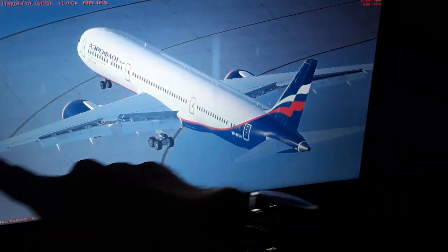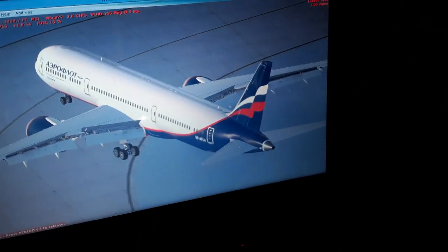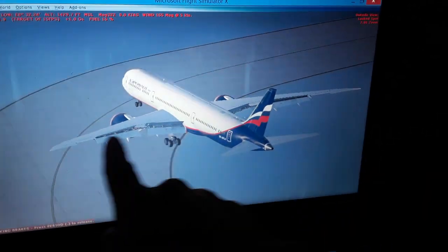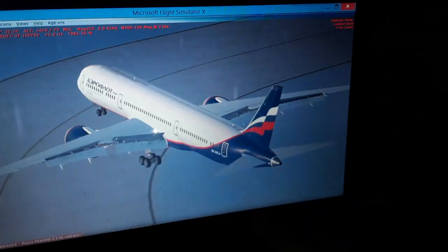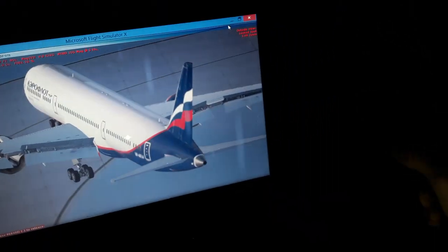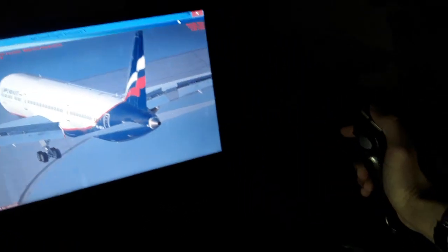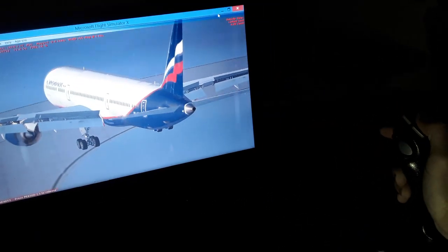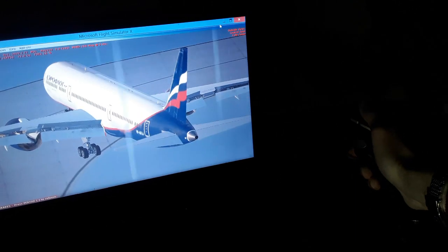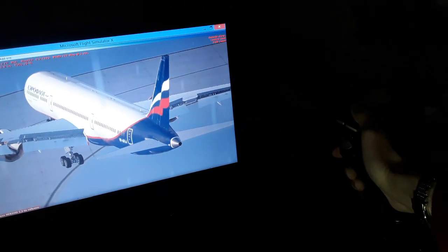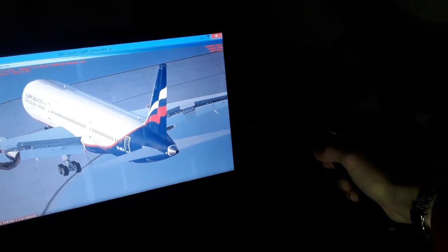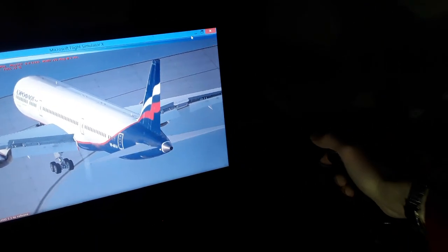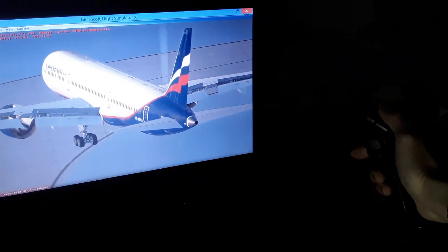We have also one more axis, the lateral axis, from wingtip over here to wingtip. It is the pitch axis of the aircraft. You use the pitch axis from the tail of the aircraft, the elevator over here, climb, descent. So you can climb the aircraft using the horizontal tail, the horizontal stabilizer in some aircraft, and also the elevator trim. So you can trim the elevator or the stabilizer, and also use the side stick in the Airbus, back and forth.